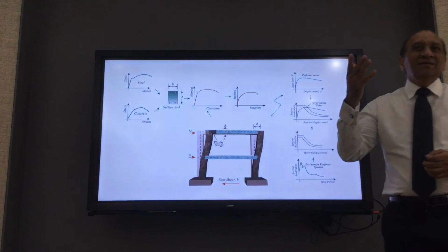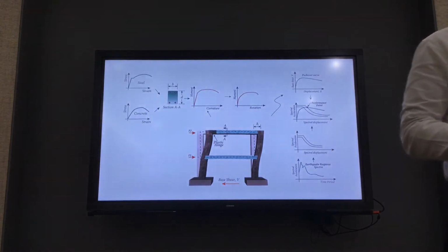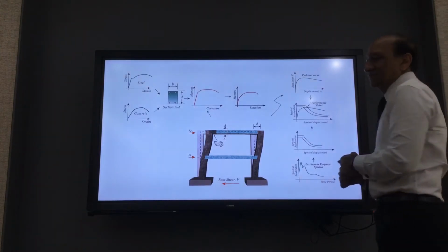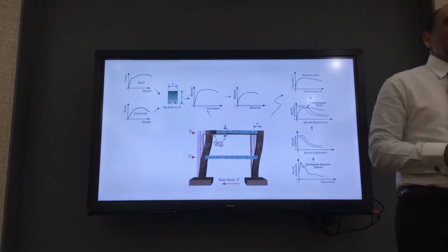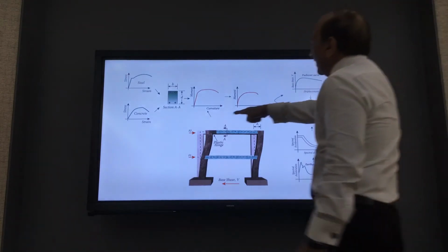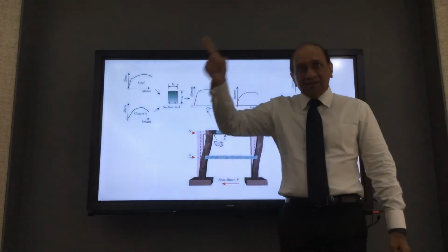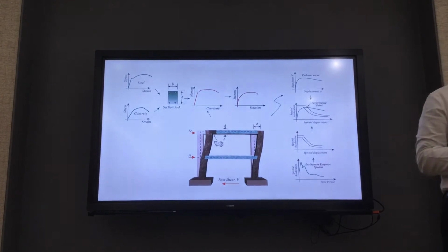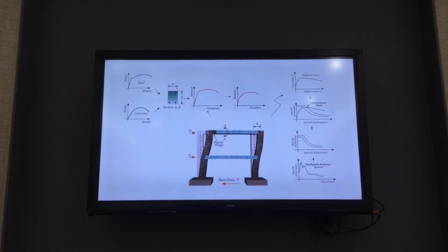But in tall buildings, higher modes and multiple modes are important. So the method becomes not so useful. What is the third objection? Big objection. Cyclic degradation. If you remember our blue curve, it goes up and down. This is only based on one direction. It does not include the cyclic damage of the structure. So the damage of the structure due to cyclic loading is not apparent in the method also, right?